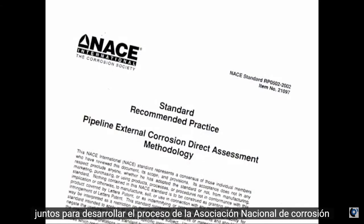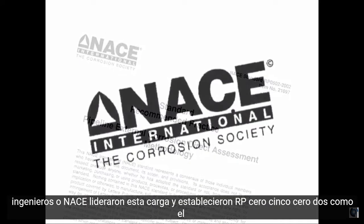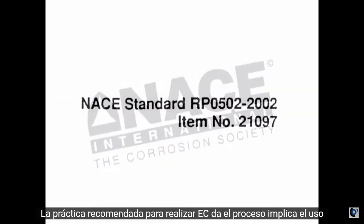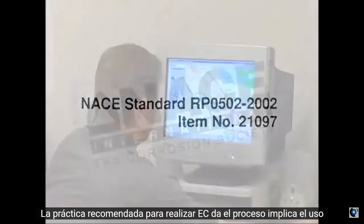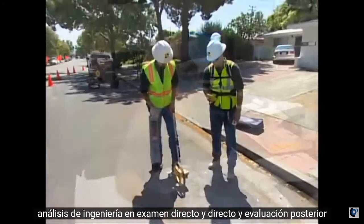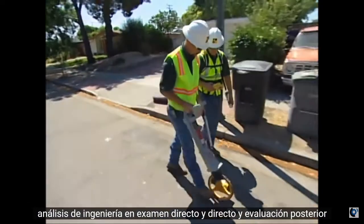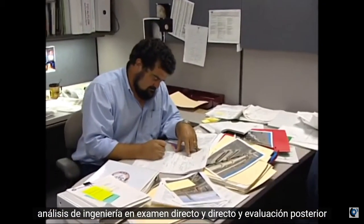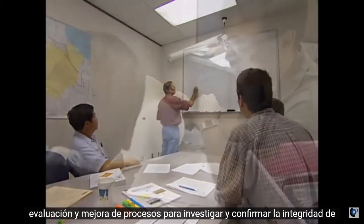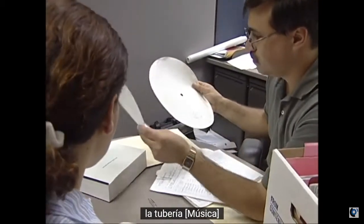The National Association of Corrosion Engineers, or NACE, led this charge and established RP 0502 as the recommended practice for performing ECDA. The process involves using engineering analysis, indirect and direct examination, and post-assessment evaluation and process improvement to investigate and confirm the integrity of the pipeline.